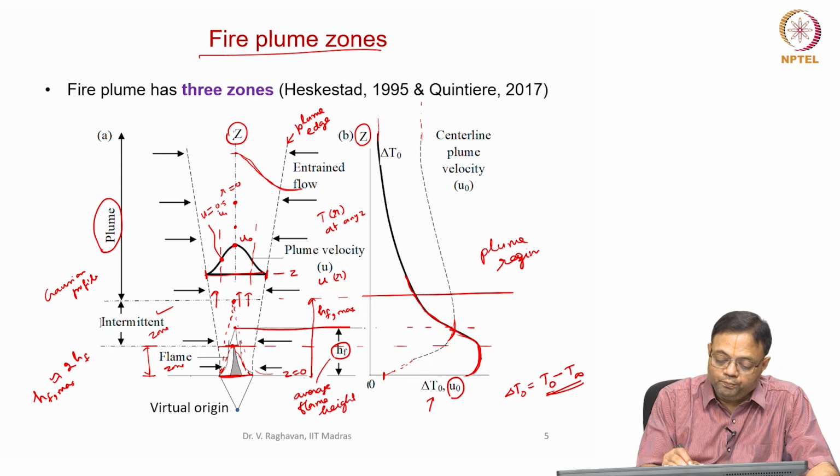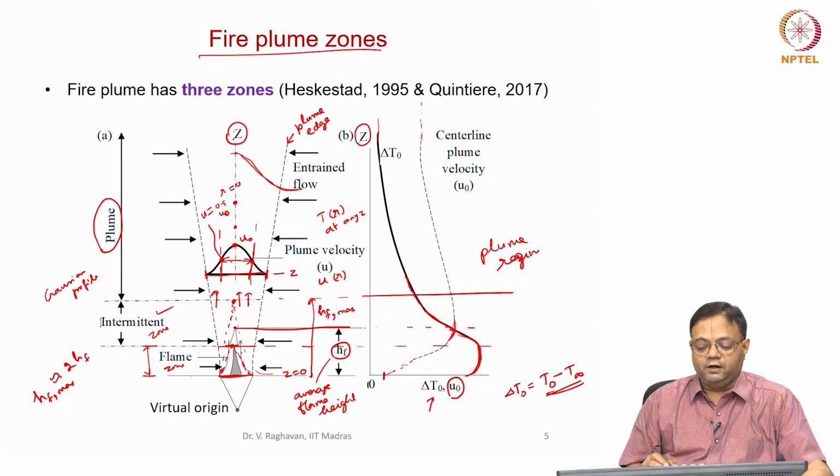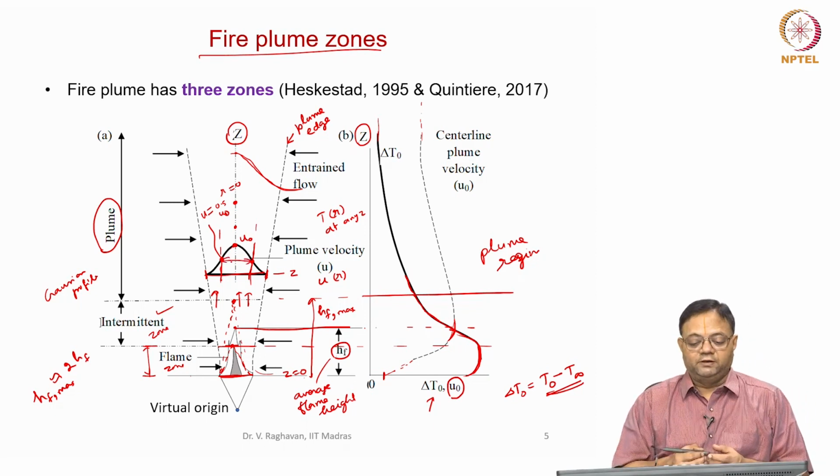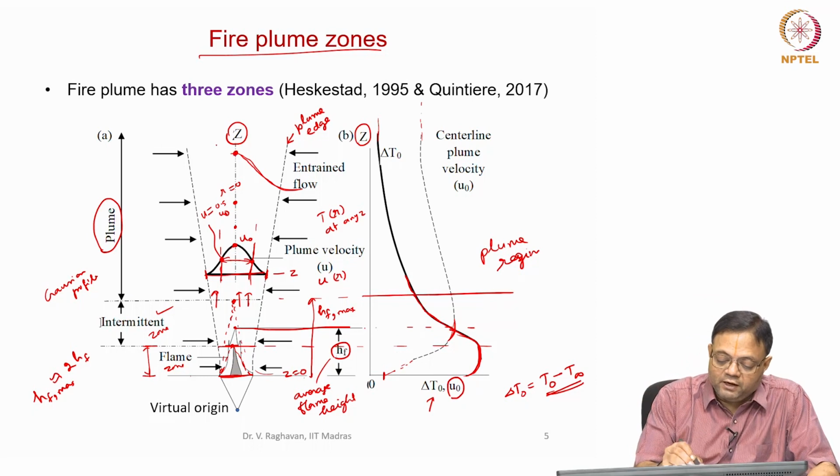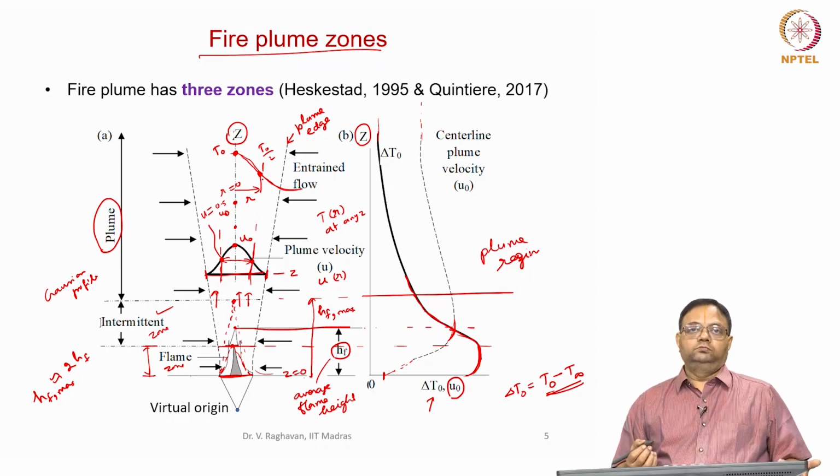Okay. So, this is the diameter for me, where the velocity is reduced to 50% of the center line velocity. The distance between these two will be taken as the plume diameter. Similarly, temperature. The temperature here is T naught, and at a particular value this will be T naught by 2. So, this location I will take as the radius of the plume and so on.